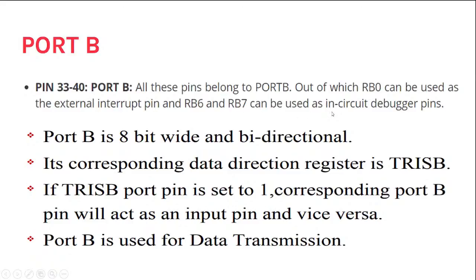In-circuit debugging is for hardware debugging. It means you can connect the hardware as well as the software, and you can keep breakpoints and watch points. You can stop the execution of the program at a particular point and then analyze the register values and the memory values. That's the advantage of in-circuit debugging.